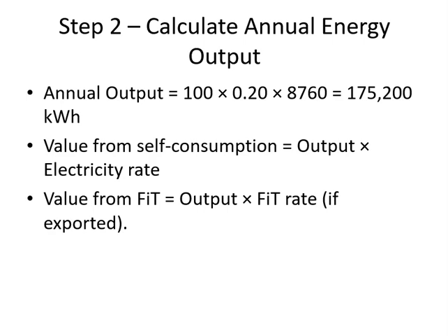It also depends on the number of sunny days. The number of sunny days in Jordan is completely different from the number in London. So in London, we will increase the capacity factor by 0.2 or 0.23, but in Jordan or in Dubai or in any other country, we will reduce it to 0.17 to 0.2.